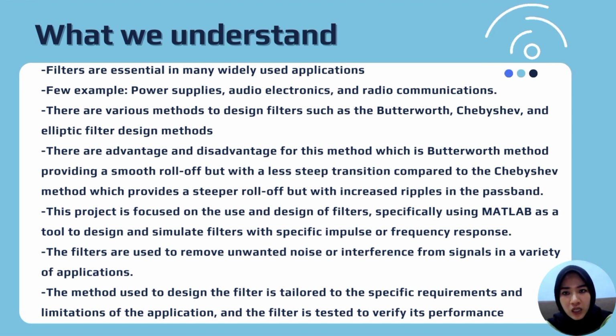Overall, filters are required in a wide range of applications, including power supplies, audio electronics, and radio communication. There are various filter design approaches, including the Butterworth, Chebyshev, and elliptic filter design methods. These methods have advantages and disadvantages. The Butterworth method offers a smooth roll-off but with a less steep transition compared to the Chebyshev method, which provides a higher roll-off but with ripples in the passband.